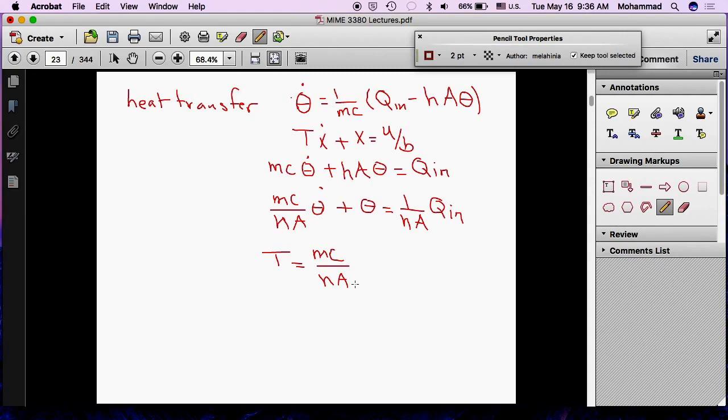It's like the drag. It is as if you intentionally try to lose more heat, but that's the key to a faster system. So both increasing H and increasing surface area would increase your heat loss, but it makes the system faster. And reducing the mass and reducing the heat capacity also will make the system faster. Any questions?